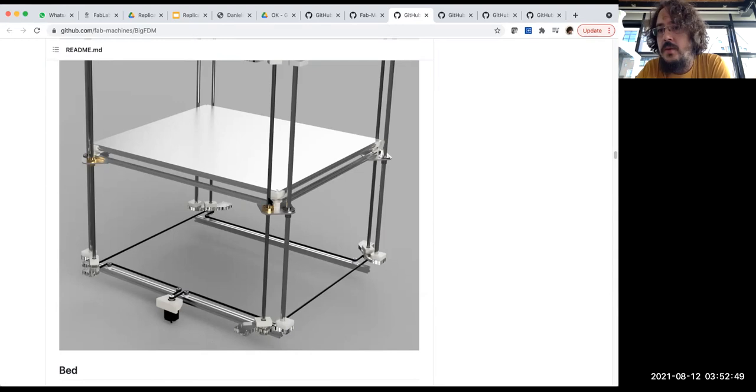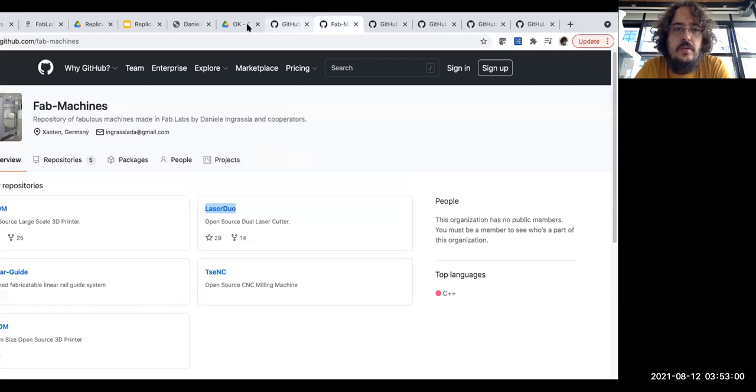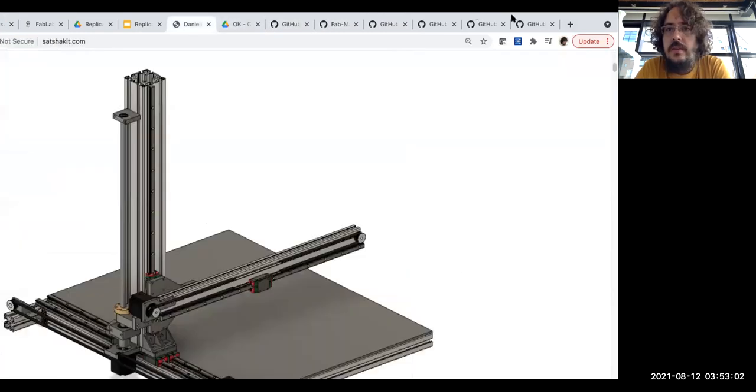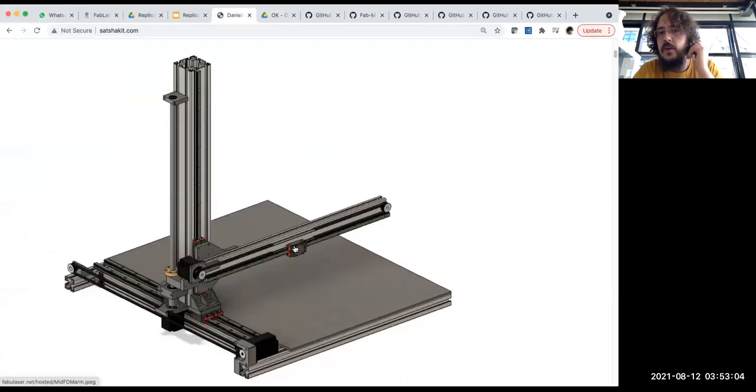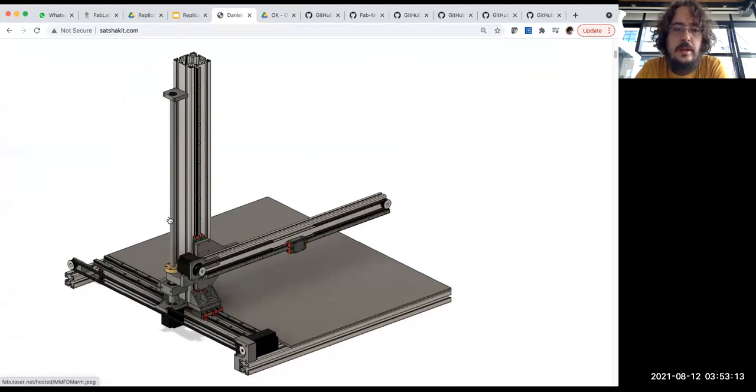I don't know if you had this problem with very old laser cutters, that if you went too far down, it blocks after a while. So the aim was to create a simpler system with much fewer components. For example, I would use only a single rail for the Z-axis to go up and down, and a single lead screw instead of 4.